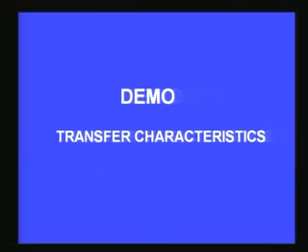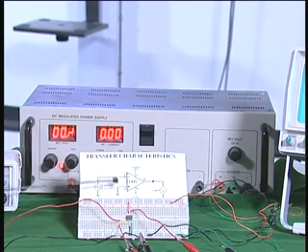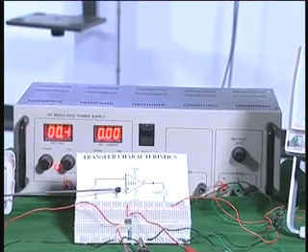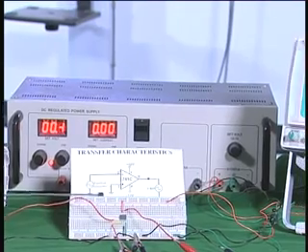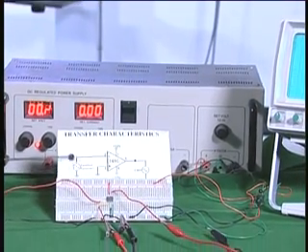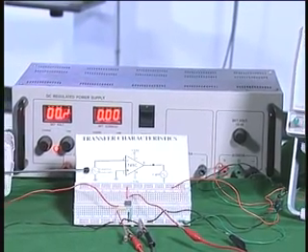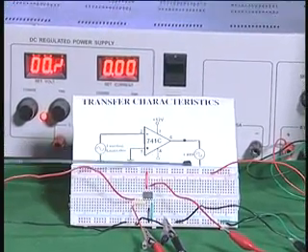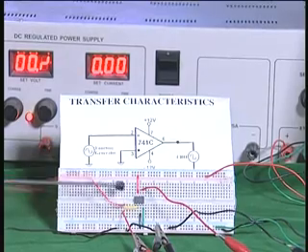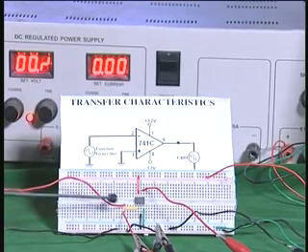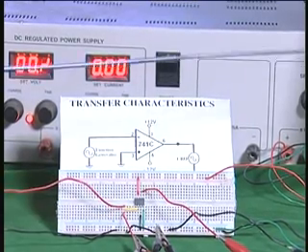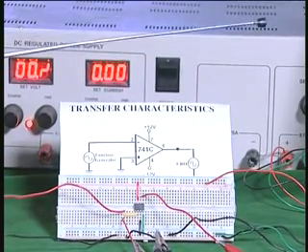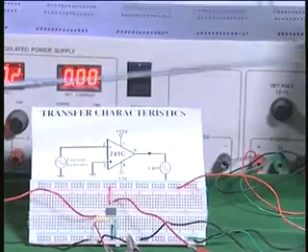So, you can see the circuit I have is a very simple operational amplifier, the same 741 with 2 inputs. One of the inputs is grounded, connected to the ground. To the other input I am connecting a variable sine wave oscillator, and the output is connected to the oscilloscope. So, the exact circuit is here, there are no resistors, you can see there are only 2 inputs and the output is monitored. Both the input and the output are connected to the x and y terminals of the oscilloscope.